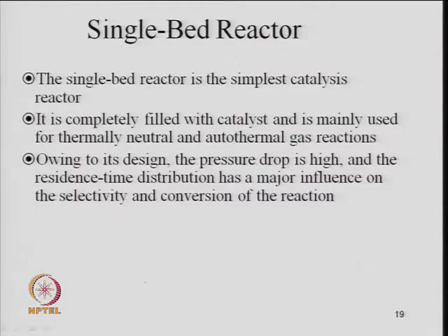So, very quickly, there are different types of reactors which are used in the process industry. If you look here, the first one is a packed bed reactor or a fixed bed reactor. So, we call it a single bed reactor. So, there is only one bed of catalyst.